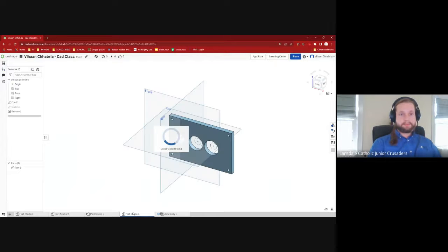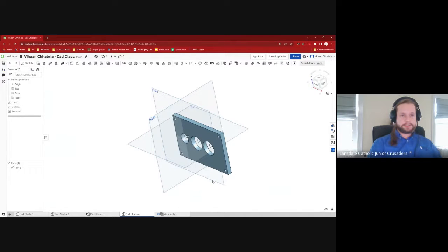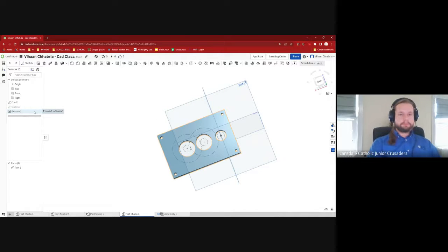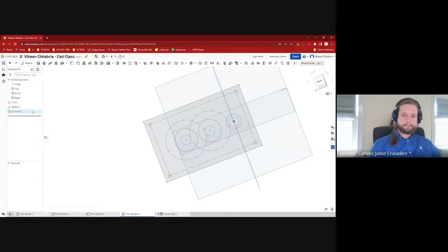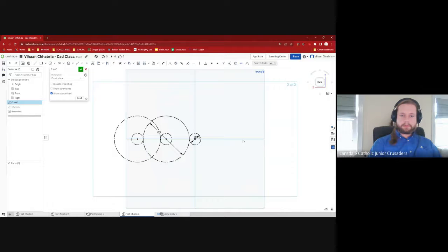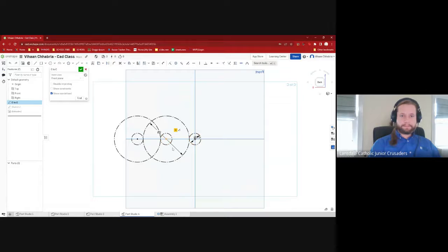Cool. And remember, you used an equals constraint on that first center to center sketch, right? C to C. Yeah. So you're going to have to delete the equals constraint between the two small gears, right? Yeah, not that one, that one. You're going to need to delete the equals constraint on that one. I would click here. Yep. Click that and then click delete.